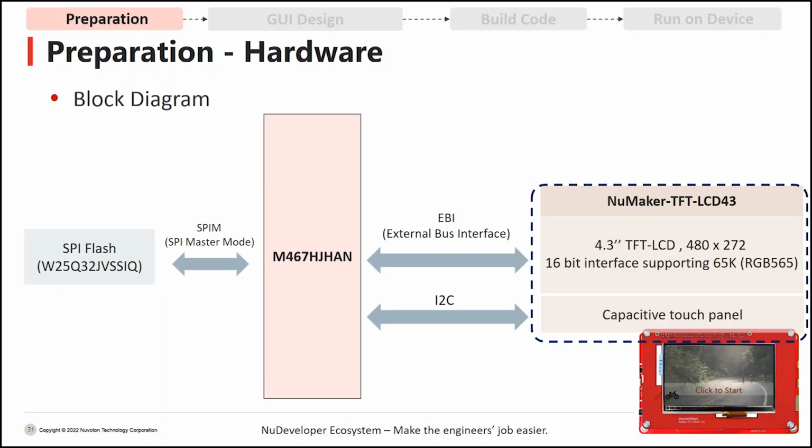From a block diagram perspective, in this example, we will use the external bus interface and the touch interface to control the screen and touch respectively. Additionally, we will store image resources in the SPIM flash and access them using the SPIM interface.